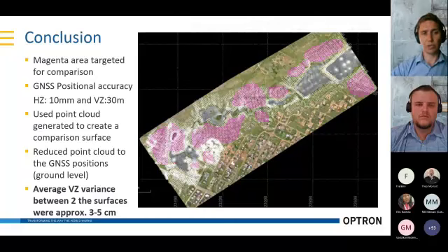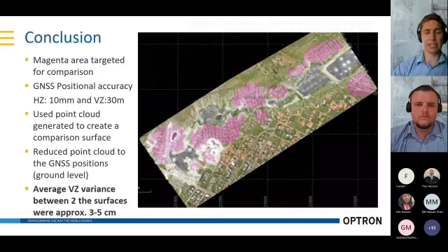So what we then did was we used that generated point cloud, and there's some nice classification features to remove, for instance, the houses, the trees and high vegetation, those kind of things. There's a feature that you can now run in TBC that does the classification for you to get you down to kind of the ground level. Okay, that is, as I've mentioned, the classification tool.